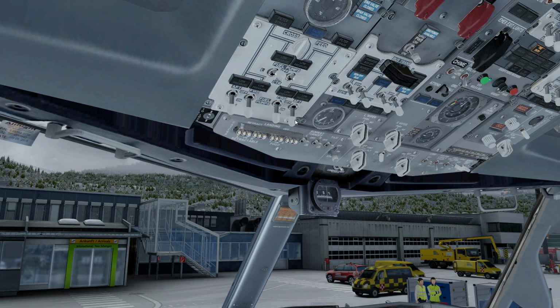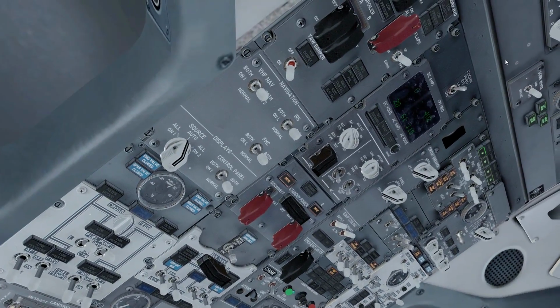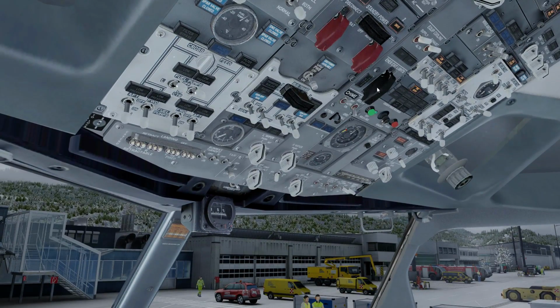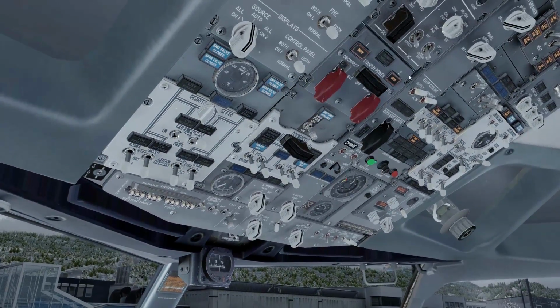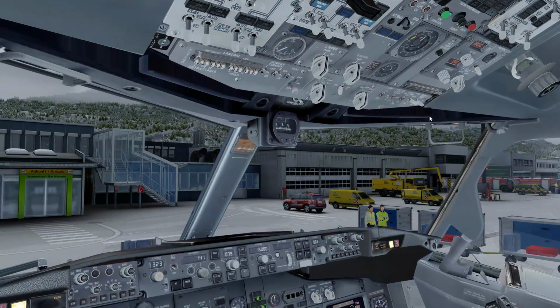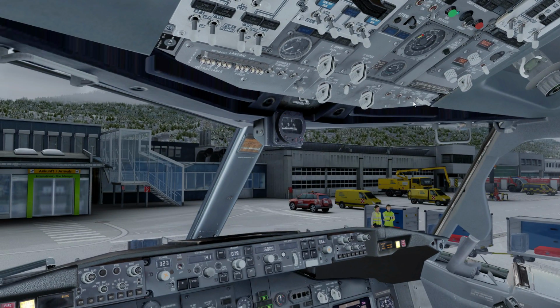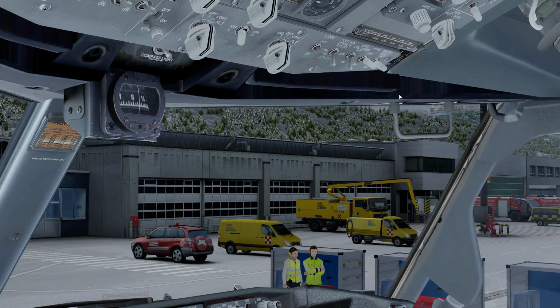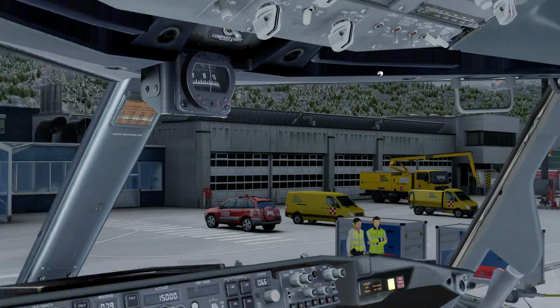So just turn on the wing tanks, right like that. And this is all still set. The APU is running. It's fine. Let's make sure everything is okay right here. Yeah, seems to be working. Well, we should have maybe turned the packs on so we have some air conditioning on board the aircraft. We're going to turn it off in a minute again when we're going to start the engines. And I'm just going to turn the anti-collision lights on right here so that the ground crew knows that we're going to be moving soon and that we're soon going to be starting the engines.